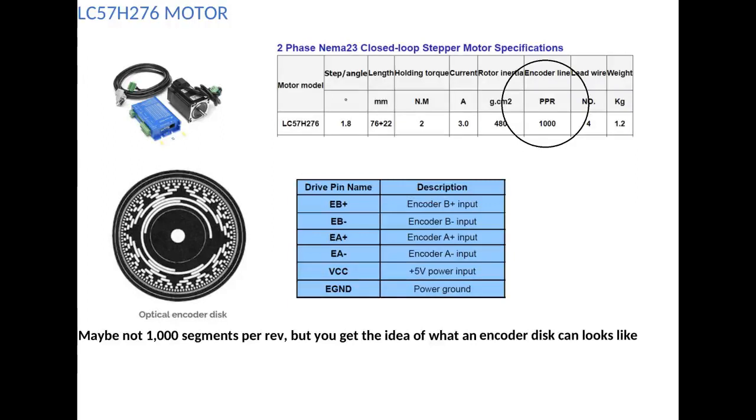The motor specification states that the encoder line has 1000 parts per revolution, which I read as 1000 discrete sensing locations on the encoder per revolution. We can see from the wiring that there are 2 encoder transmitters per encoder wheel. This arrangement is common and is called quadrature sensing, and allows the sensing electronics to determine more physical locations than the 1000 positions in the one encoder revolution.